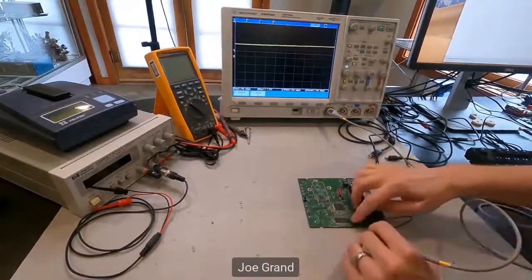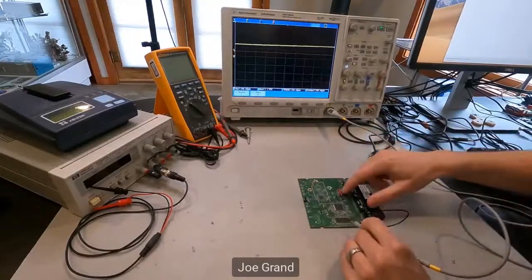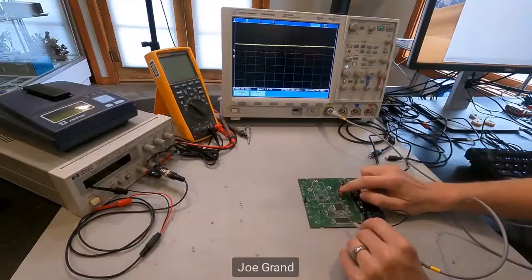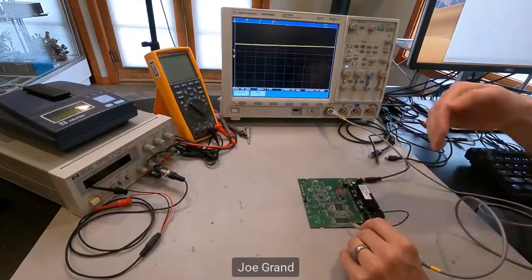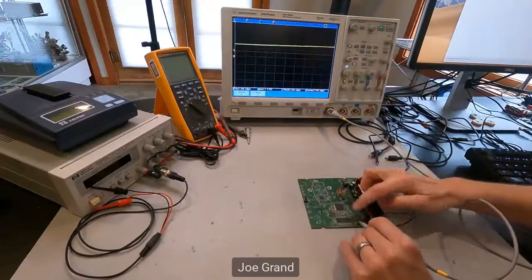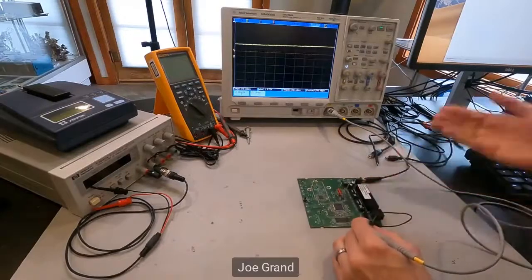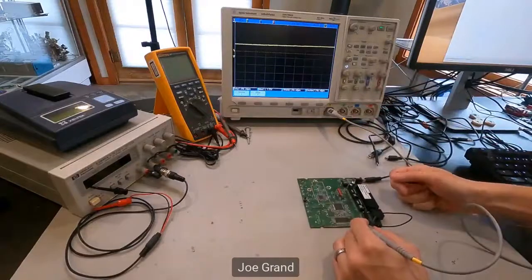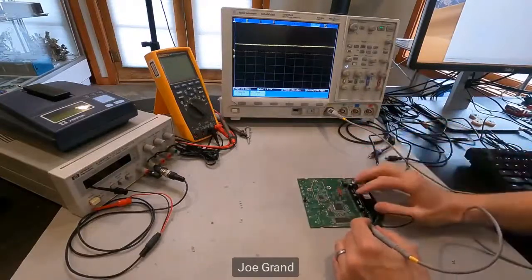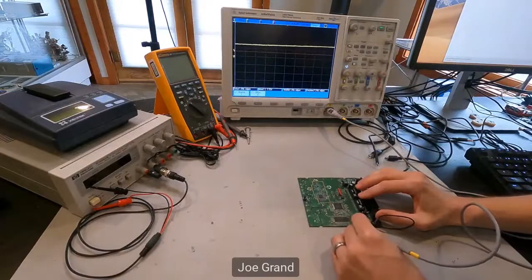Down here, this connector here, another thing that when you're looking at a board, just kind of preliminary view, is you're looking for connectors, things that are intentionally meant for engineers or for manufacturers. And I had soldered these connectors on the board. Normally, those would just be unpopulated. And those are going to be things where your eye would be drawn to those and say, oh, okay, if the engineers intentionally put those things there, they're probably interesting. So on this connector down here, this is another one that I'm interested in.